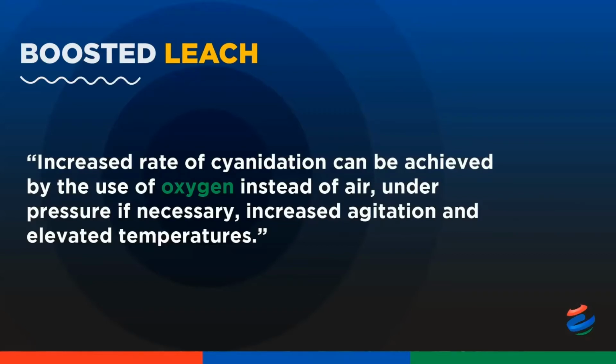All of these conditions are satisfied when we add cyanide to the Mach reactor as well, for a boosted leach ahead of carbon adsorption. Some plants manage to achieve circa 80% of the recoverable gold in a single leach tank, using the Mach reactor ahead of the adsorption circuit to create a leach and adsorption profile similar to that of an old school CIP plant.